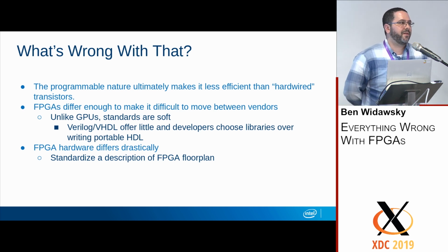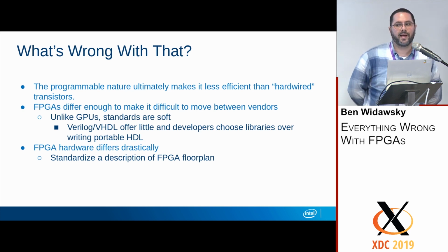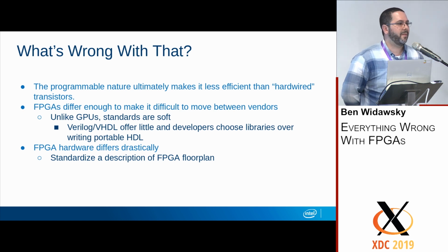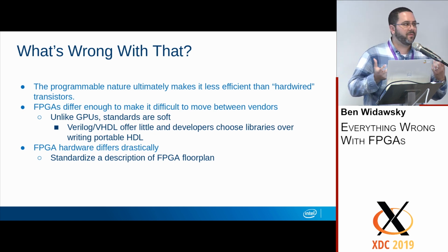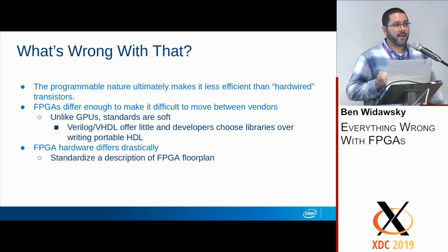The thing that really bothers me is, as I was describing this theoretical FPGA, you might have noticed that it really gives an opportunity for the hardware vendors to do things incredibly different. So both routing and what the logic cells look like and how many RAMs there are and adders and what the carry chains are connected to. And that makes it really difficult to have a single stack and sort of abstract concept of what an FPGA is, more so than you might think on the surface.